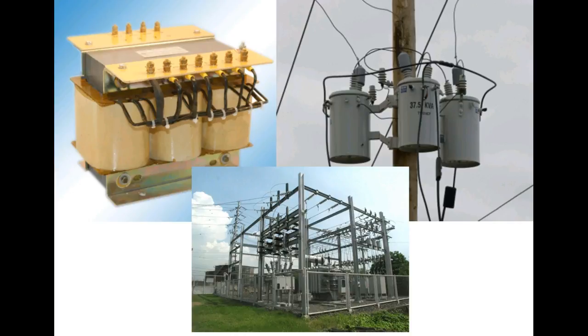These are 3-phase transformers. So anytime you see transformers in groups of 3s like this, that means you're dealing with what? 3-phase. Sometimes they use individual single-phase transformers that are wired for 3-phase, so each one of them gets a different phase. Sometimes a 3-phase transformer is built in. This costs more to install, but it's cheaper to maintain. So if one of these goes out, I have to replace the 3-phase transformer. If one of these goes out, I replace one single-phase transformer.